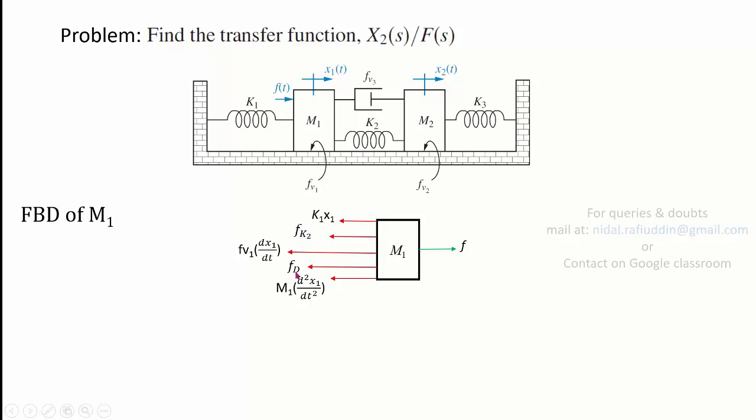So this is done in order to have the comparators involved in the block diagram representation, because if you're not going to show this in this manner, you're not going to have comparators being shown in the block diagram. So the block diagram that you will obtain, if you're not going to use these terms, will not have comparators in it. That will be a more simplified form of representation.